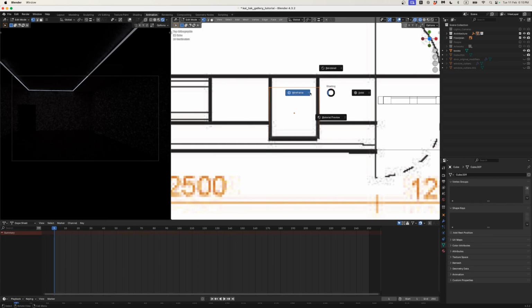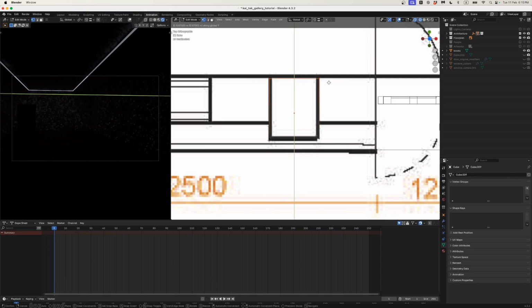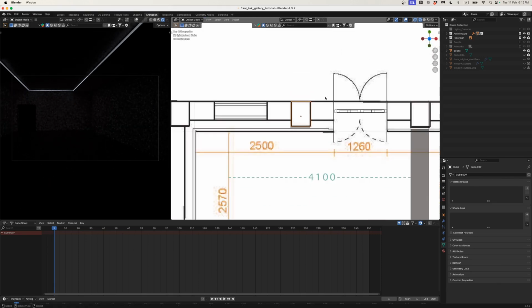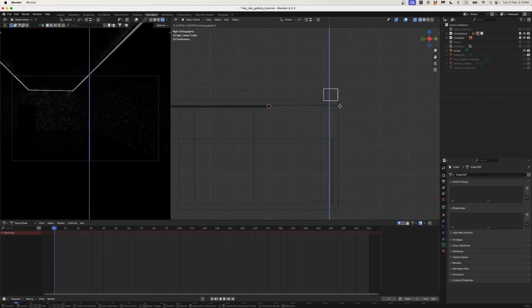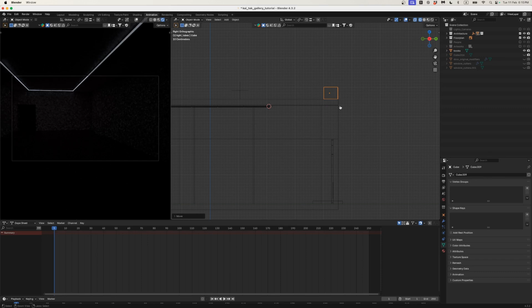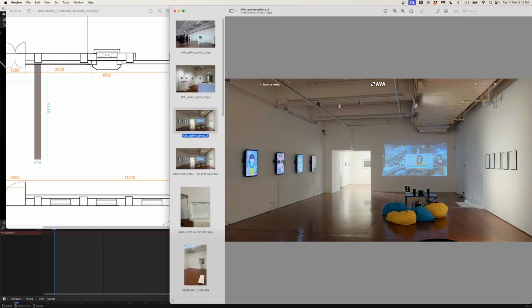I've gone into wireframe view, vertex select, dragged that, G Y to make that the correct length. But what we're actually going to do is, if we look from the front, lift this pillar up, and let's take another look at the floor plan. I'm going to take a guess here. I'm going to treat the height that we have for our roof as the bottom of these pillars.